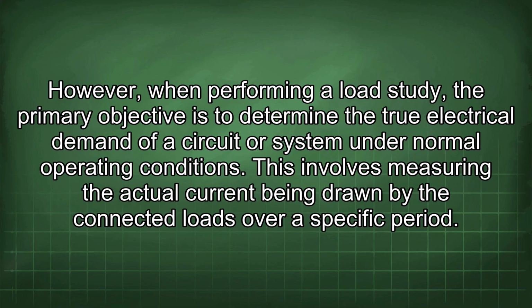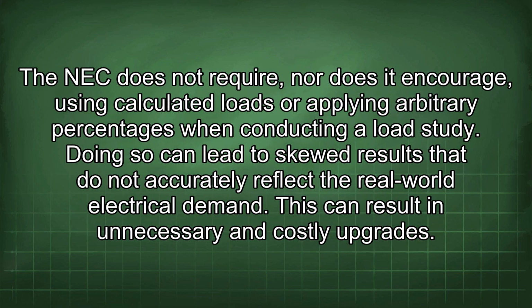However, when performing a load study, the primary objective is to determine the true electrical demand of a circuit or system under normal operating conditions. This involves measuring the actual current being drawn by the connected loads over a specific period. The NEC does not require, nor does it encourage, using calculated loads or applying arbitrary percentages when conducting a load study. Doing so can lead to skewed results that do not accurately reflect the real-world electrical demand. This can result in unnecessary and costly upgrades.